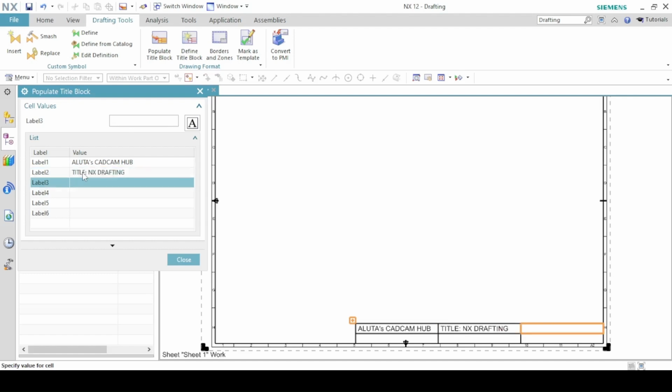Press enter. The third should be the scale of our projections. And most of the time, we want to use 2:1 scale. Now, this cell should contain the date we are making the drafts. So the date should be 20th September 2025.